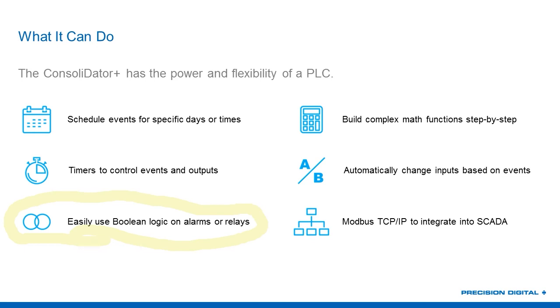Well, what I can do is set up a high alarm for each individual tank, and then create a combination of those. I would take all of those alarms and create what I call an OR alarm. And that OR alarm will trigger the light. So no matter which tank it is, if any of them go into high alarm, I can throw that alarm. So that's the very basic example, but we can do AND or OR alarms, or NAND and NOR alarms.